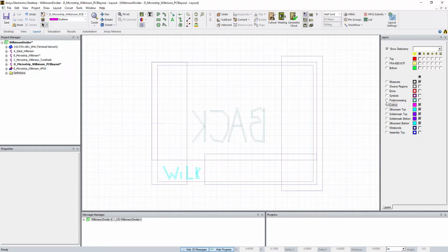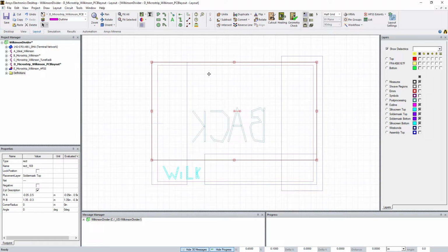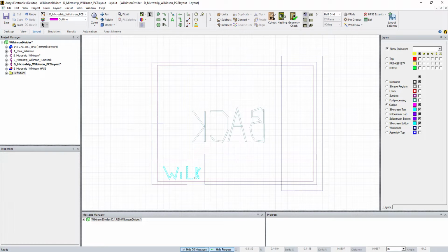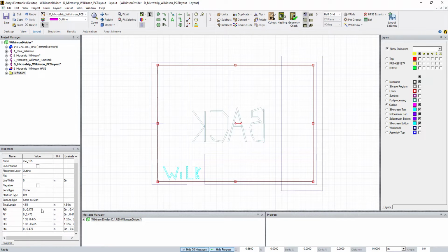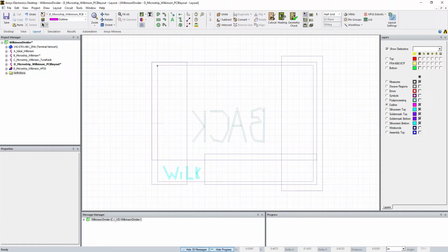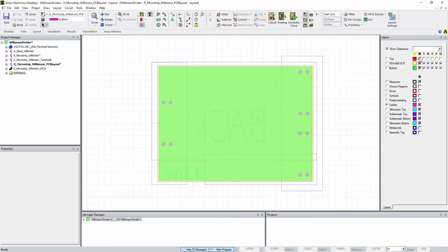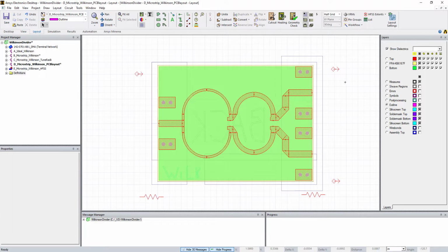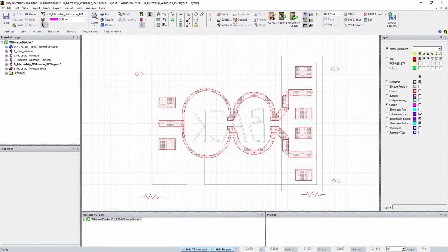We talked about the outline layer, that kind of goofy thing where the outline, click on the right one, is defined by 4 points. All these other ones are defined by the 2-point blocks. And I think that's pretty much it for defining the whole circuit board. At this point, when you have all this done, you can generate Gerber files right from here. You don't have to go to the next level because you've defined each of the layers. So just kind of go through it real quick. You have your top layer, which is defined by your traces.